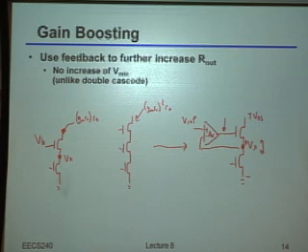And by the way, I want the precise answer this time. What is it? I heard somebody whisper, just speak up. Is it Av minus 1? You're very close. We just need to flip one sign somewhere. There we go. It's 1 plus Av, right? Because notice, even if that gate didn't move at all, you would have gotten a change of Vx, so it's actually 1 plus Av that is the change in gate to source voltage.